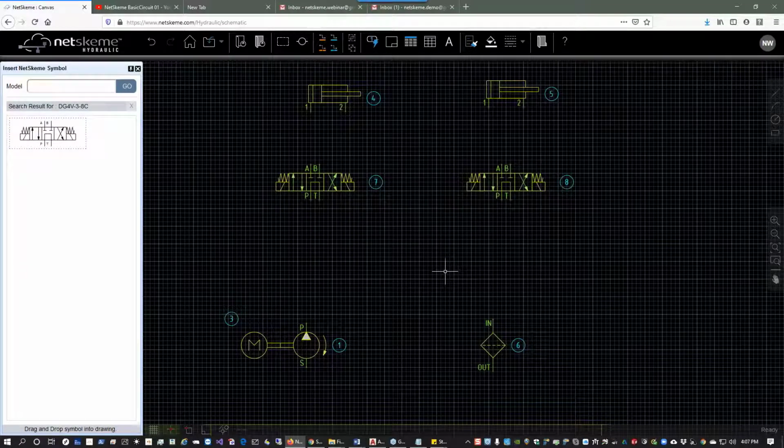After the symbols are inserted, smart connections can be performed. Note that 4 connection line icons are available within the ribbon menu: pressure, reservoir, control, and drain. After selection, a connection is initiated by hovering over the symbol until the green circle appears, indicating a qualified connection point. Then clicking. Similarly, clicking on a connection point on another symbol establishes a smart connection using intelligent routing.